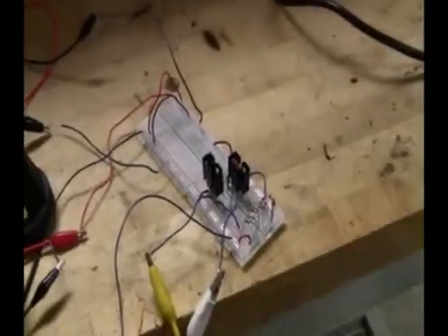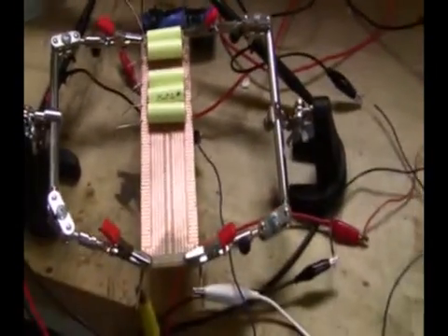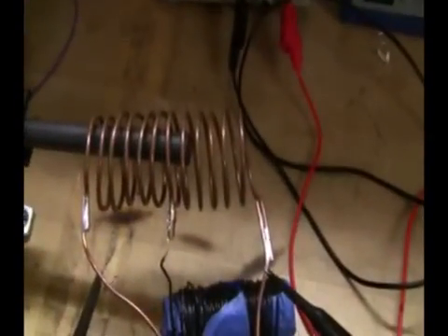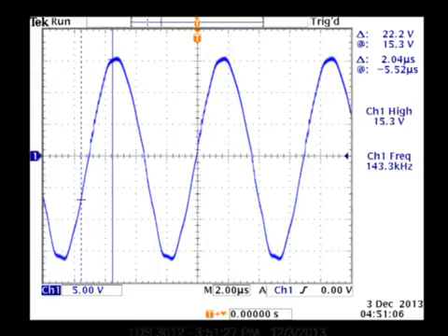In our first attempt at creating the circuit, our estimation of the inductance in our resonant tank circuit was much lower than our actual value. This caused the circuit to resonate at a much lower frequency than originally guessed. The power delivery of a single power supply wasn't enough to get the object up to a sufficient temperature. In order to raise the resonant frequency, we removed several parallel capacitors from our resonant subsystem.